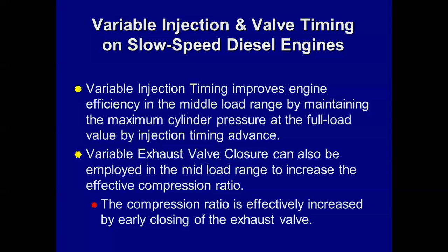Well, you can change the timing of this exhaust valve on the newer engines to allow you, when you're running at low loads, to increase the compression, which increases the temperatures and the pressures in the cylinder to give you a better burn at low loads.